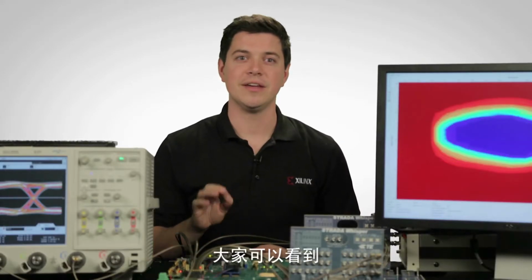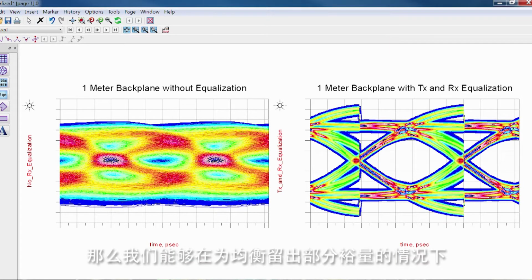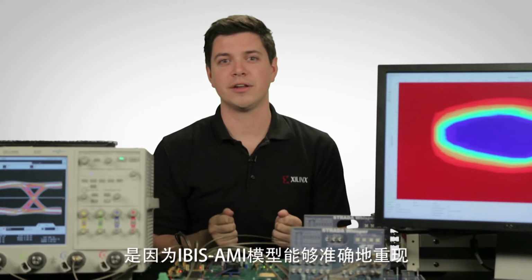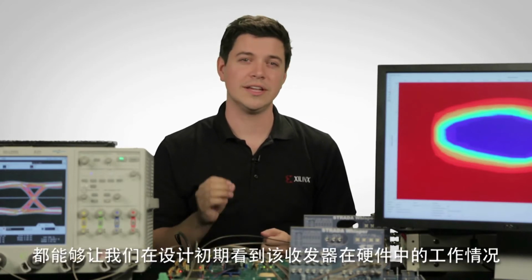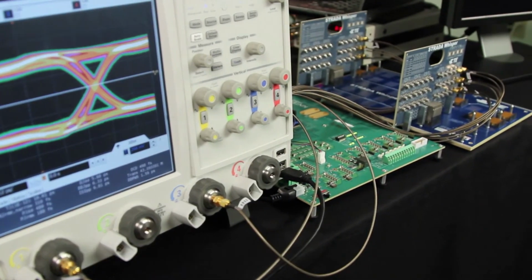You can see that at the input to the receiver on the FPGA, the eye is completely closed. Yet we're able to recover the signal and have an eye at the CDR with some reasonable margin due to the equalization. This is possible because the IBIS AMI model is able to accurately reproduce the effects of our second generation auto-adapting AGC, CTLE, and 11-tap DFE, giving you an early look into how this transceiver will work in hardware, in this design or your own.